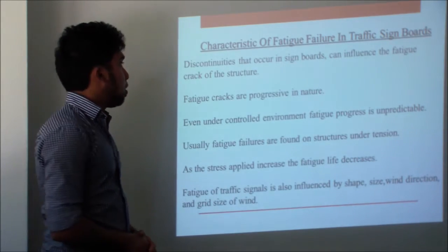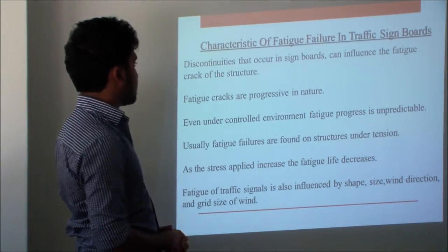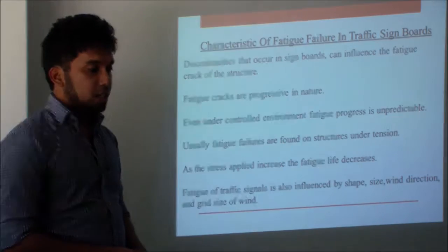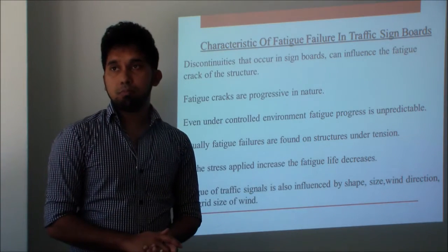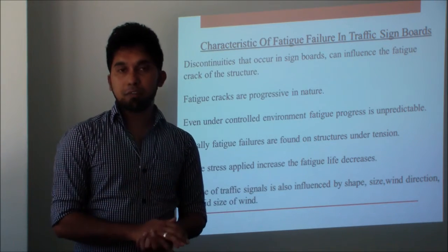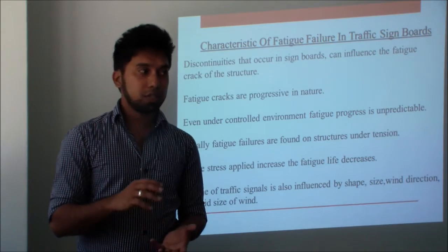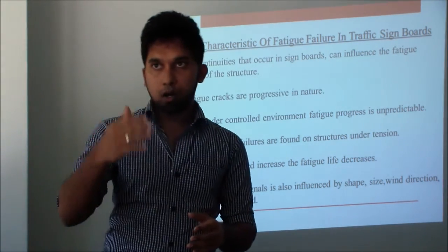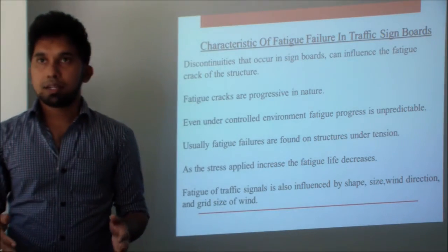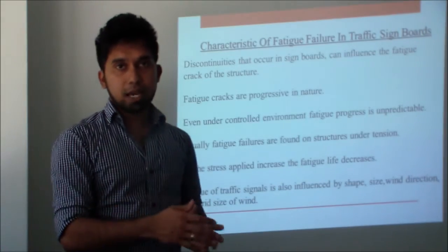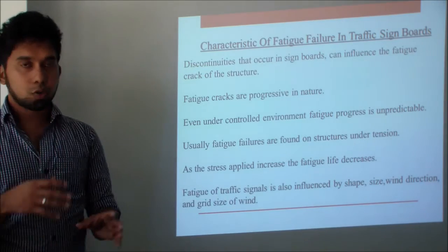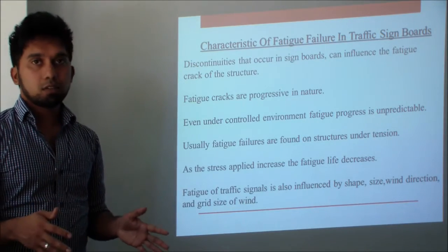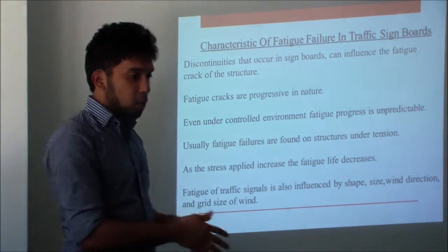The characteristics of fatigue failure in traffic signboards. The main characteristic found in fatigue failure is discontinuities in the signboards, like holes, maybe separations. All these can contribute towards fatigue due to increasing concentrated stress at these points.